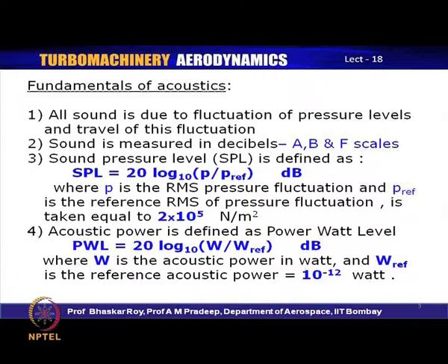The sound pressure level, as I mentioned, sound is actually a pressure fluctuation. So, sound pressure level is defined as SPL, and that is 20 log 10 P by P reference, and it is measured in dB or decibels.